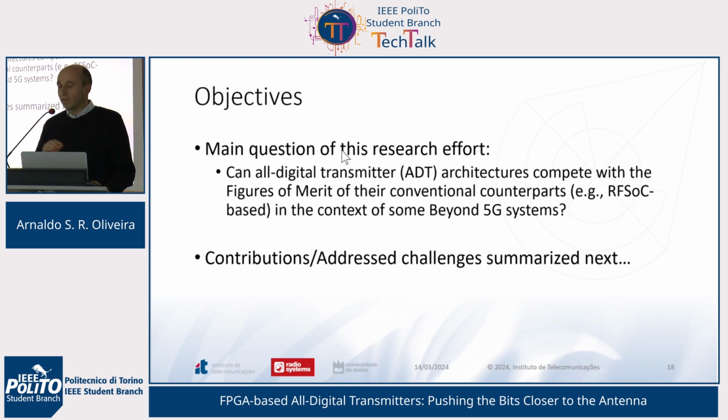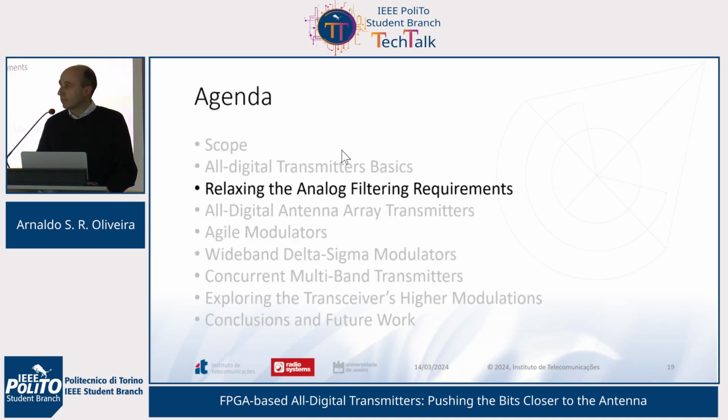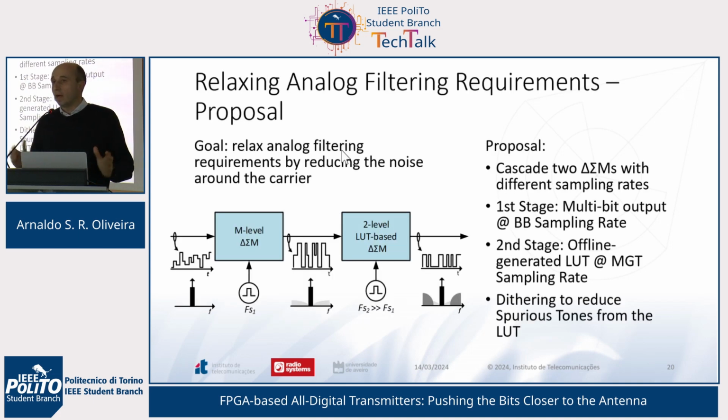What I will briefly summarize next are our contributions, the challenges we addressed over the last 10 years, starting with the relaxing of the analog filter requirements. Independently of whether we use PWM or delta sigma, we will always have our desired signal and noise around it that needs to be filtered.